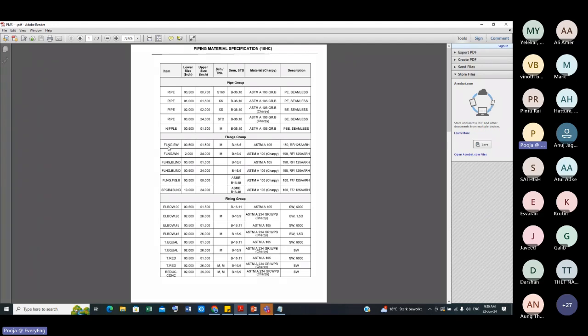If I want to buy a flange, then I'll say my flange should be of class 150 rating. What should be the end connection? It should be the raised face or the RTJ. I have not covered the facing of the flanges in this session. It's not possible to cover everything, but these parameters you have to tell. Again, I will give the analogy of buying a mobile phone.